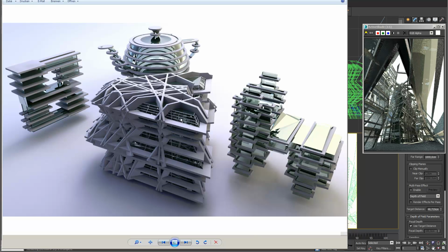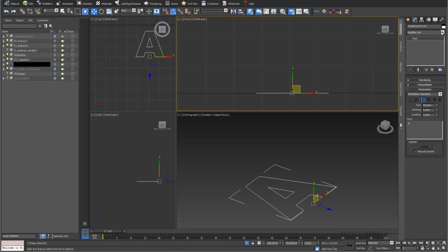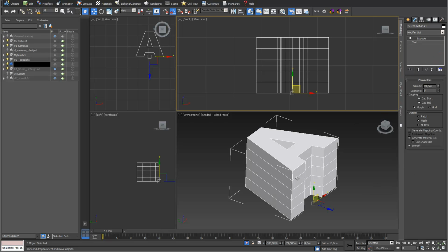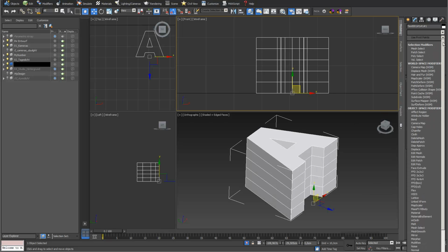In this video we will learn how to develop complex sectioning models like you see in this picture in a really easy way. I just start with a really easy shape. I just put an extrude modifier on top. I have 5 segments. Next step, I want to deform this a little bit.